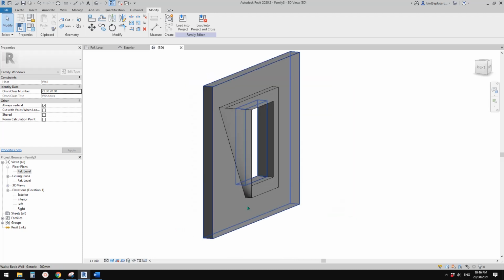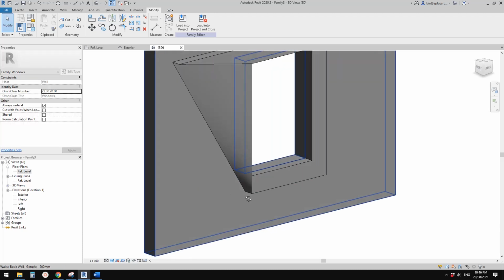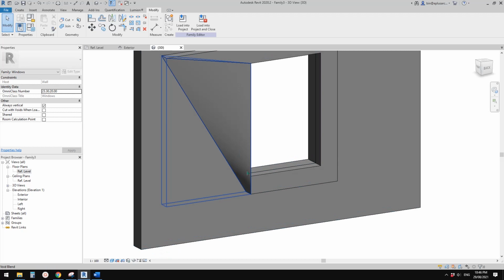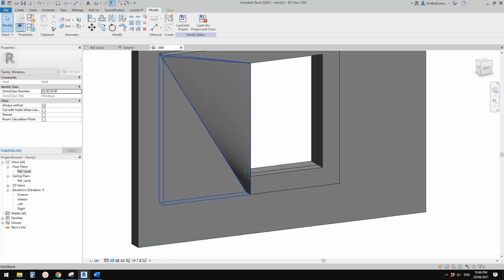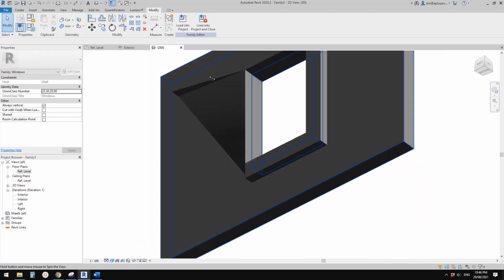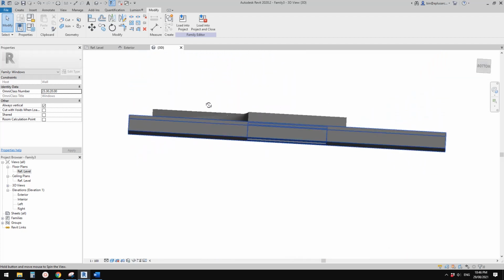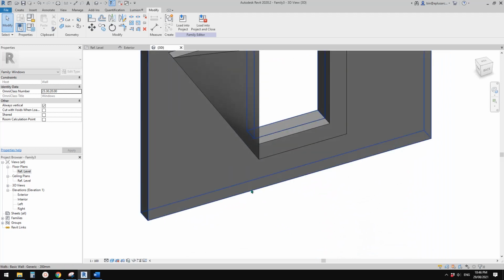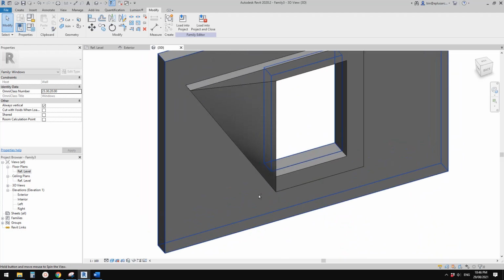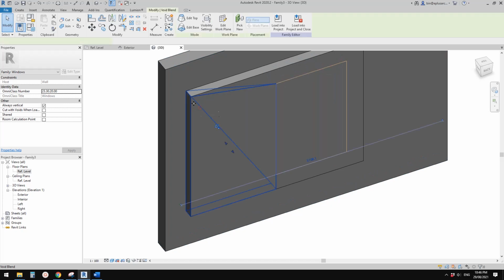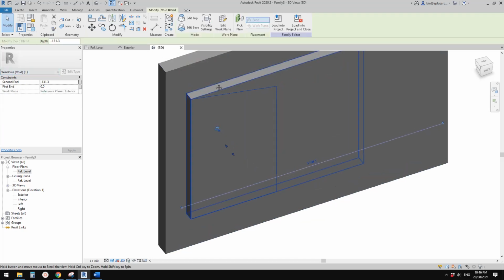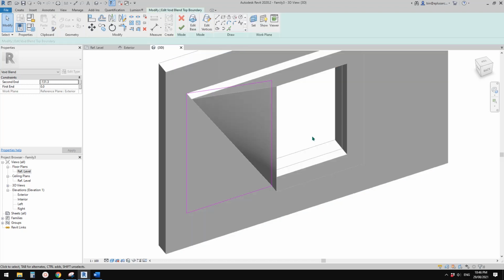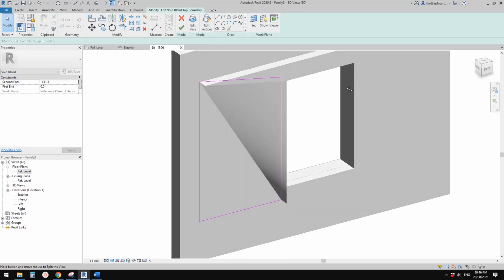Almost there, but you will notice from the shade. So from this shade, this means it's curved. It's not flat. So if you rotate it a little bit, so you can see that's a curve. So what we need to do is we need to select this void. So select this blend. Okay, so void blend. So edit top or base, doesn't matter. So click on edit top, and then so see this one.